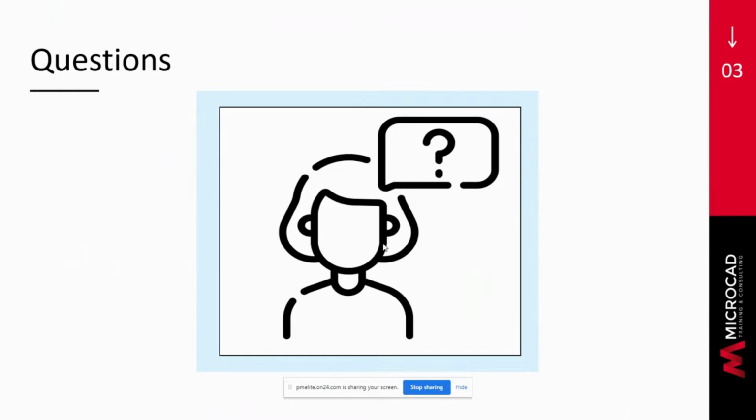So sometimes we have to do that more manually. You can pick the profile in the graph and move things, or you have to edit vertices a little bit more manually. In the case of a surface profile, we can't, but the surface profile will move if you do a datum adjustment on the surface. So 50-50 on that one. Now, corridors are tied to profiles, so whatever you can shift on the profile, then yes, the corridor will follow. I hope that answers the question.